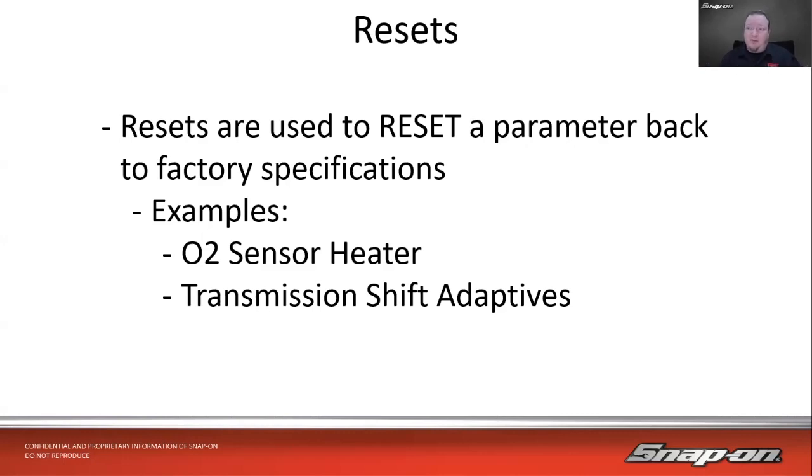And same thing with transmission shift adapters. If you think about any time you do any transmission work, it's going to shift differently. Do any valve body work, solenoids, bands, or whatever. As the transmission adapts, it's going to adapt to whatever the wear level of the transmission is, all the parts inside. So if you do replace new parts, you could have harsh shifts, things like that. So you need to reset the transmission shift adapters.